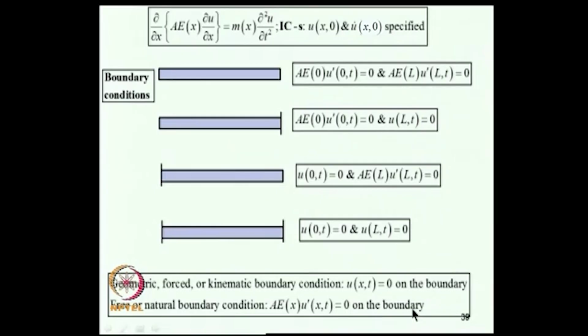So, the important aspect of applying Hamilton's principle is that it not only provides us with the governing field equation, but also it provides us with the necessary boundary conditions that have to be used in solving the governing partial differential equation. Whereas this may be obvious for the one dimensional problem that we are seeing here, for many other more complicated problems what the boundary condition should be is not something that can easily be specified by inspecting the geometry and other details of the problem. It needs to be derived by applying the variational arguments.